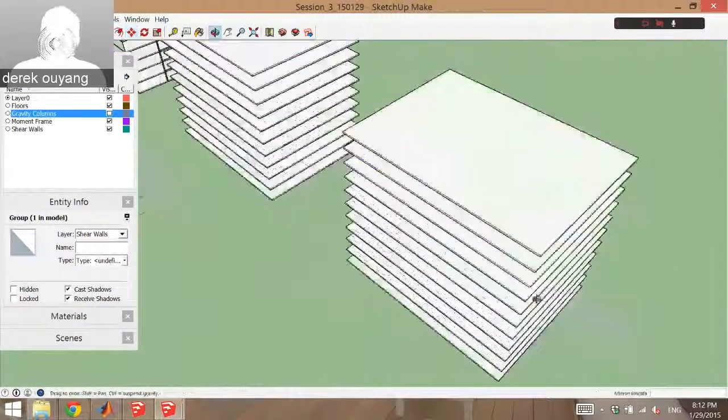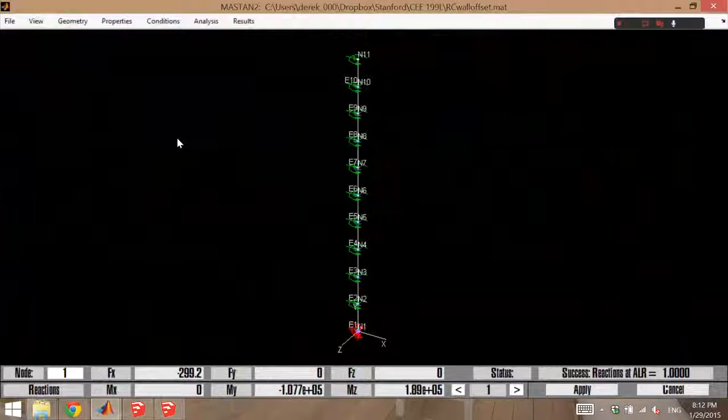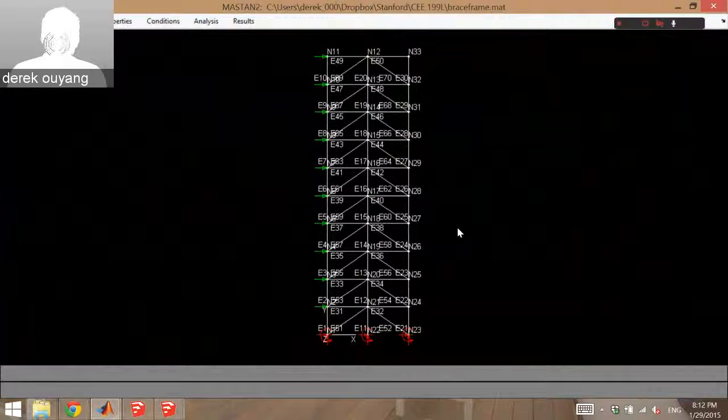So what can you do for the third tower? I'm just going to show one example if you want to go this route. You could do this, right? So all I've done is I've created sort of like a chevron on each floor. What you'll notice is that it decreases significantly the amount of forces that the lowest column experiences. And so what you've done is you've taken away a little bit of your material from your vertical column, vertical member, and then you're adding these bracing members. And that could be a really good solution if you're tight on space. Any questions overall? You go back to the sketch.